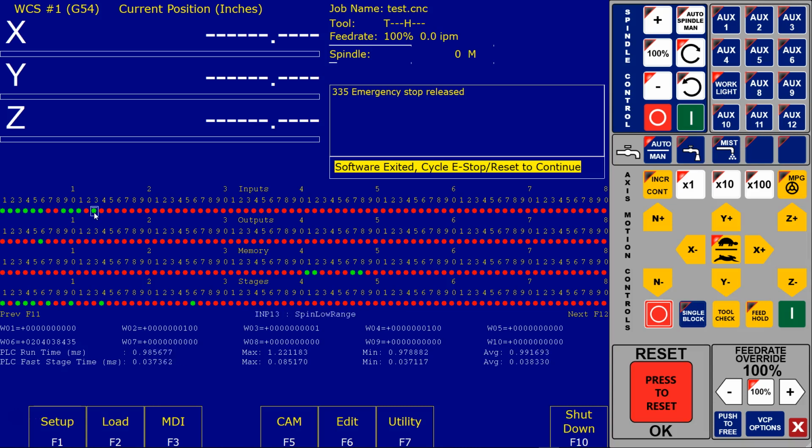Okay, this is definitely going to be needed for anyone that's going to wire something and is using normally open inputs. Now, one thing that I've seen in the past is that these inputs 1 through 6 on a DC system are your limit switches. By default, in every PLC program, these are your axis limits for the first 3 axes. And of course, you've got 2 per axis, a plus and a minus side limit.